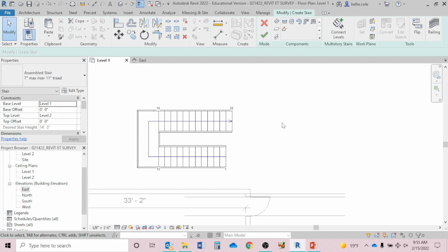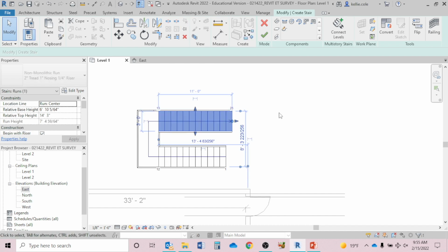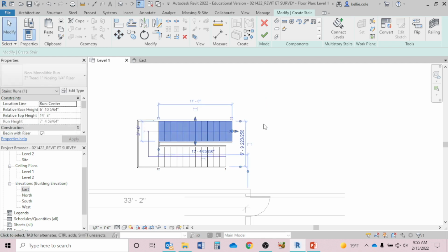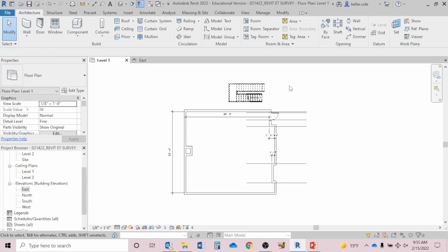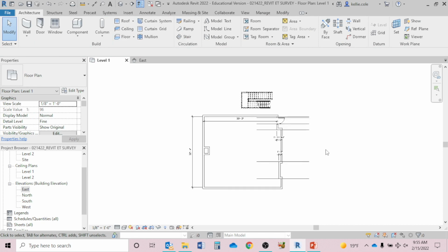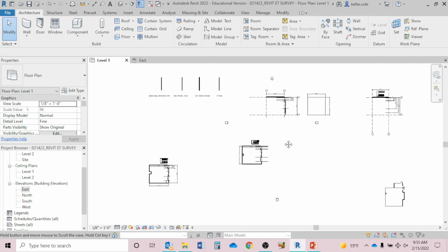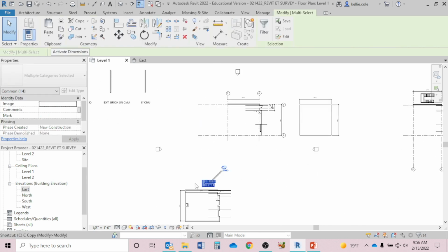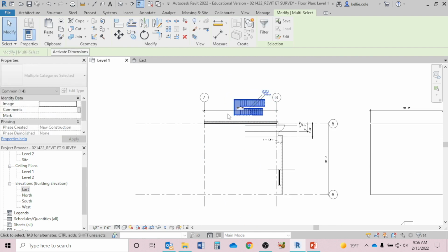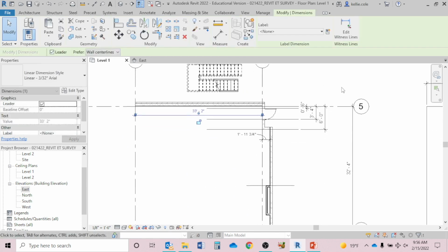Great. To move the stair closer together, click the one you last drew. You can type MV for move, or you can use the arrow keys to do this imprecisely. Okay. Click on the side of the drawing and hit the check mark and zoom out. That was method 2. Earlier, we drew method 1. This method also has a stair now, and both classes are ready for the next lesson.